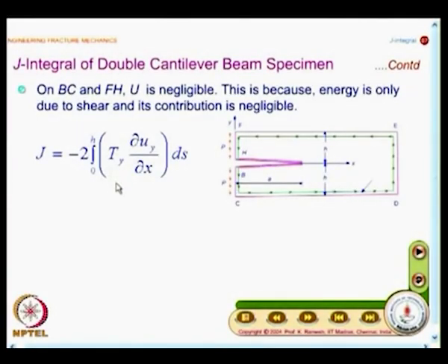You recall your knowledge of the deflection of beams. When you look at the deflection of beams, it is nothing but the slope of the beam at the free end. And can you write the slope of the beam at the free end? If you want to find the tip deflection for a cantilever with an end load, a very famous formula is PL³/3EI, where L is the length of the beam. Here we are taking the length of the beam as a, and the slope is PL²/2EI.